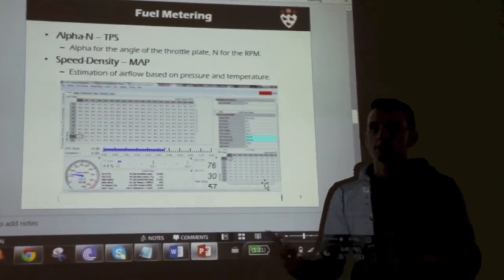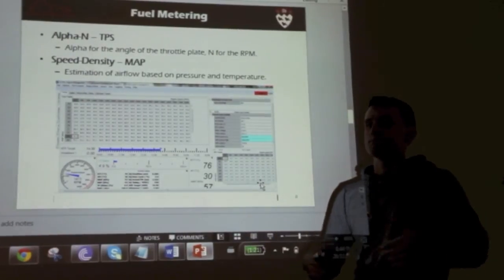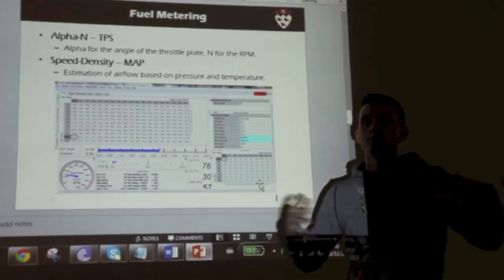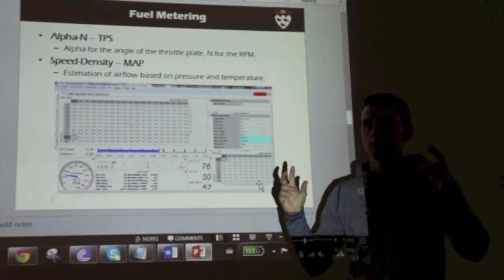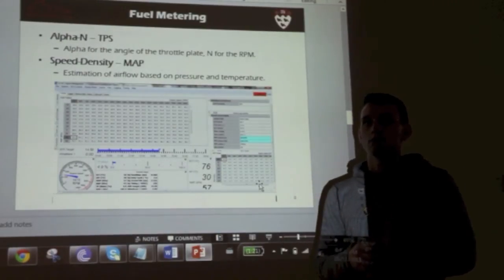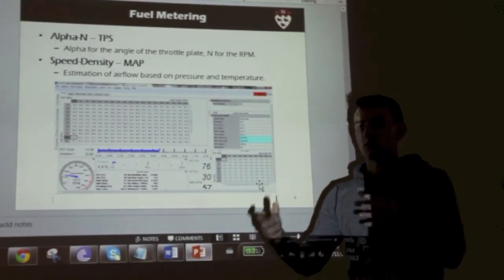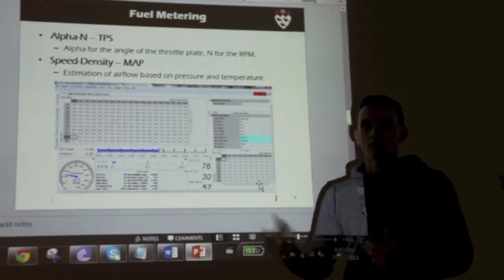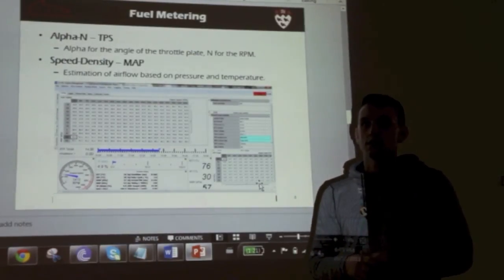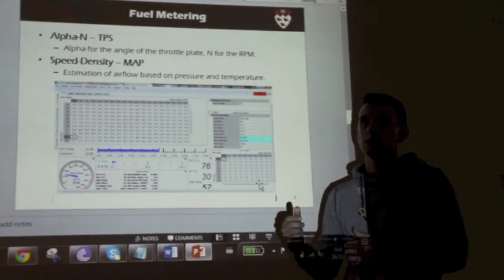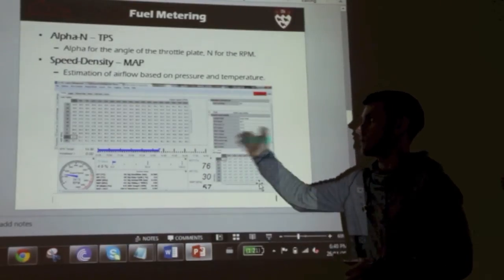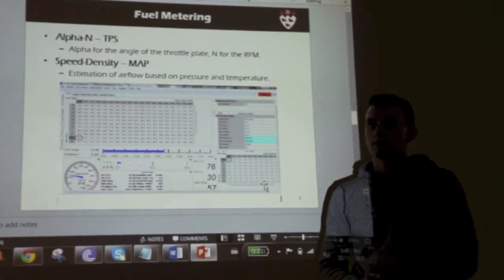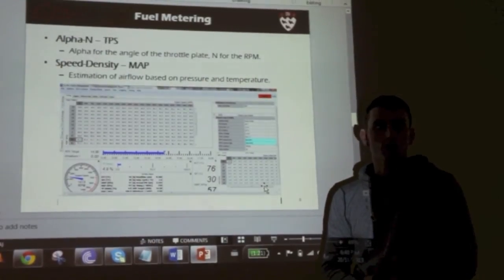For us, instead of having large drums that are being rigged, we have a small water turbine, and you essentially control the flow rate of the water through the turbine, and that supplies your load that you then use to control your engine to define its operating conditions.